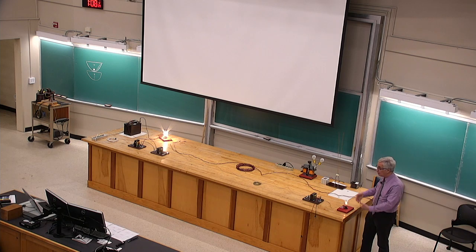It now has a 4-volt voltage drop, which means it doesn't carry very much current, because you've got to push hard on the current to get it through here. So it doesn't carry nearly as much current as it's supposed to, probably down by about a factor of 3, and that current, as it goes through, drops off less energy per unit of charge. So it's a double whammy. It's not getting enough power, energy per time, to light up properly.